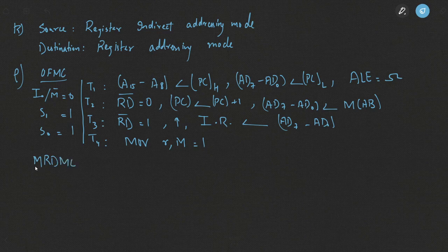and that's the memory read machine cycle. So what happens with the memory read, with the read operation? We have seen that for a read operation S1 will be 1, but S0 will be equal to 0. Fine. It has only three T states, T1, T2 and T3. Each will last for 0.32 microseconds. In the T1 state now,